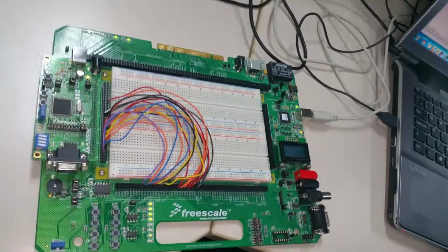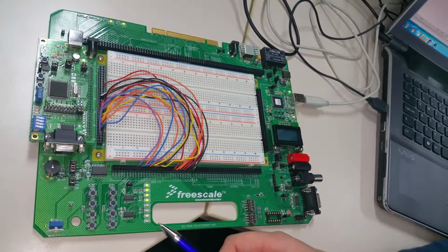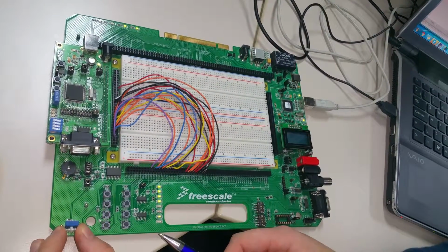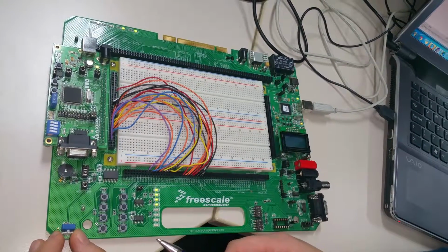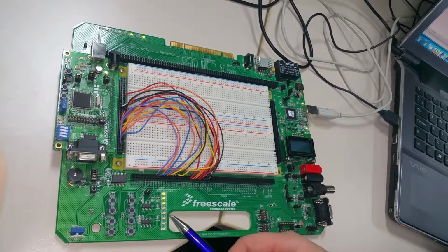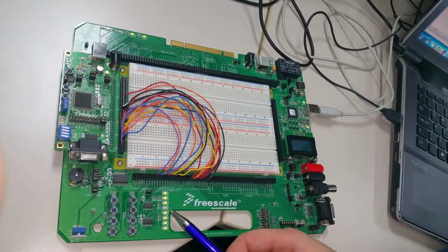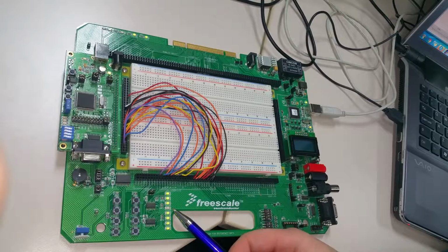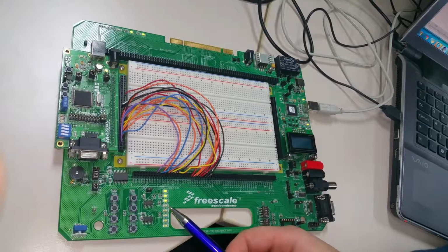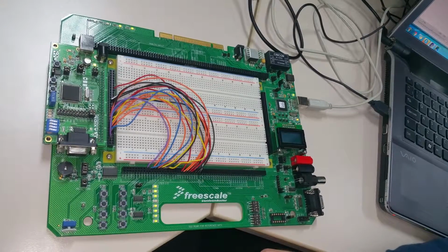The final feature I would like to demonstrate is if the oven malfunctions and begins to overheat. I would simulate that by increasing the actual temperature higher than the set point. You can see that all of the temperature indicator LEDs begin flashing. This is because they're now in the error state, and you can see that LED number 4 has gone out, which indicates that the oven heater is no longer on. This is again a safety function. In this state, the oven would naturally cool down, and then the technical fault can be investigated.